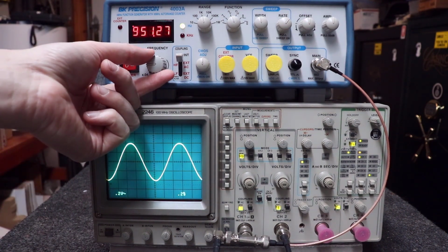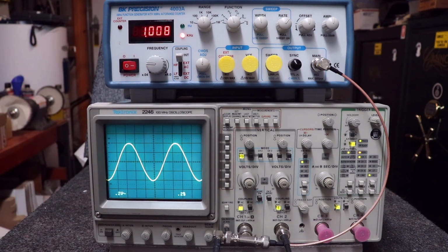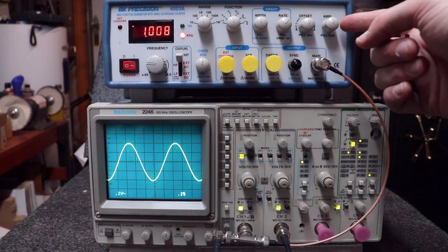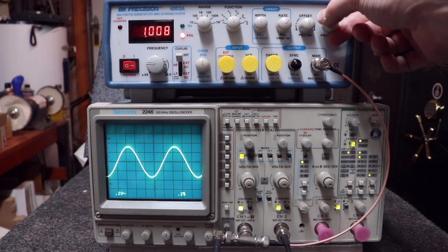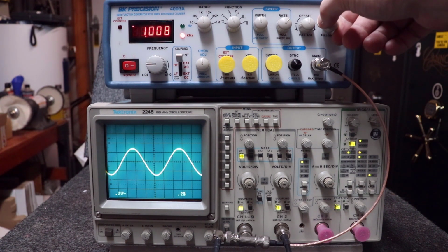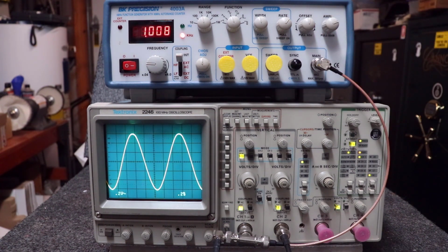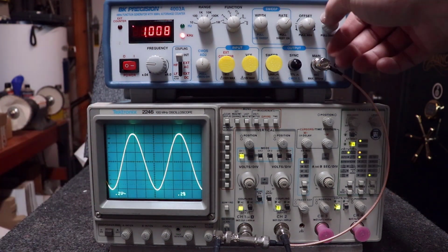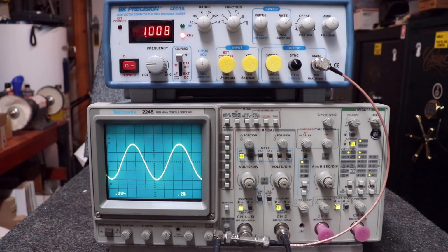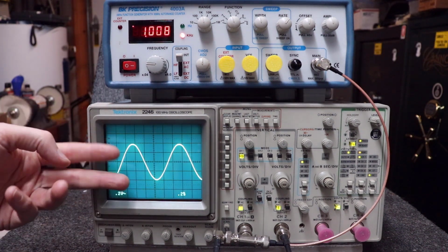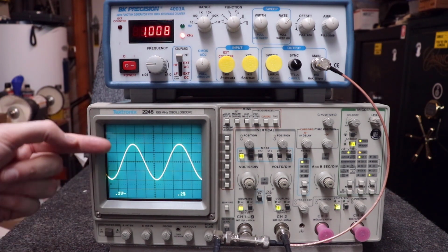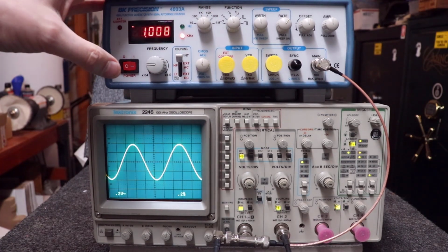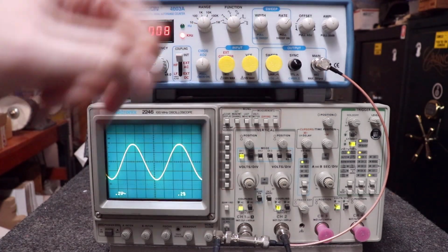So I will be adjusting this little knob here, and when I do, I'll tell you I'll be adjusting the frequency, and we'll see it going this way. Next knob here that we need to concern ourselves with is the amplitude. So watch what happens when I turn it, okay? The signal gets bigger. In other words, more volts peak to peak, so the signal gets bigger. Less volts peak to peak, the signal gets smaller, okay? So if I talk about varying the amplitude, that's what I'll be doing, and we see that increasing or decreasing here on the y-axis. That's really all I'll be doing with this unit today. So frequency, shape, and or amplitude.